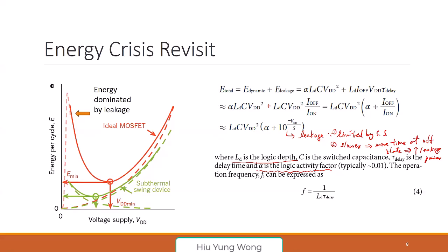This curve is going to shift in this direction. Lower energy with lower power. Okay? Because if you try to change your logic for the same technology, you might not be able to get lower energy, right? For example, I try to reduce the VDD, you might go up the energy, right? So that is the idea, right?